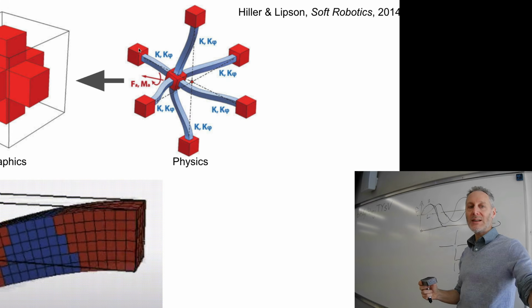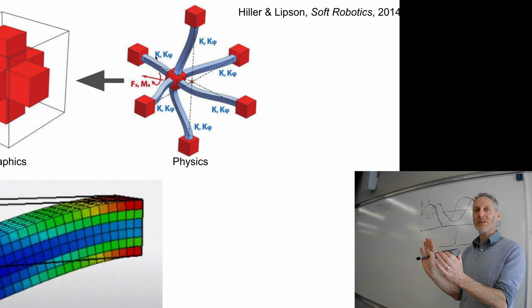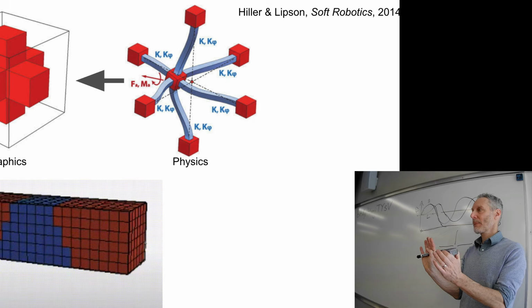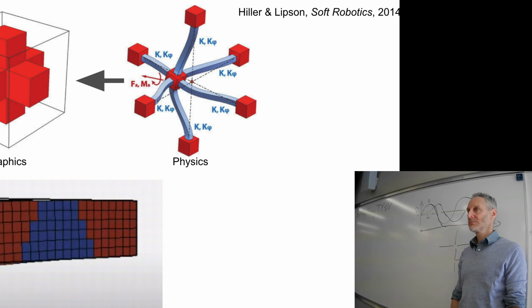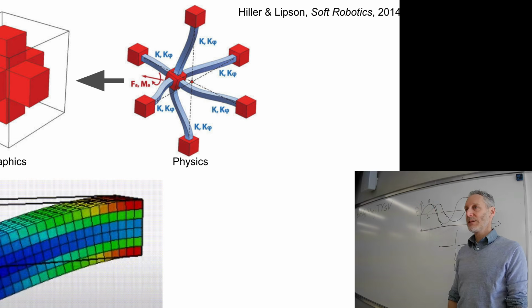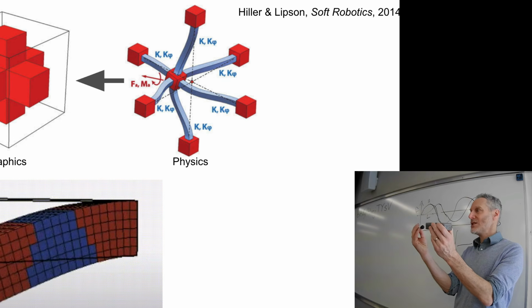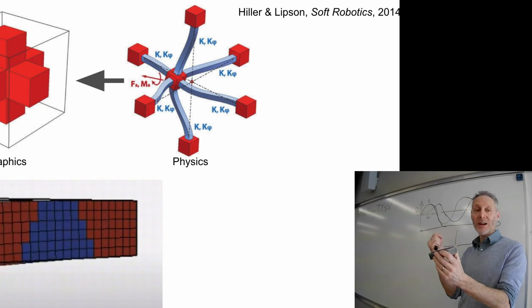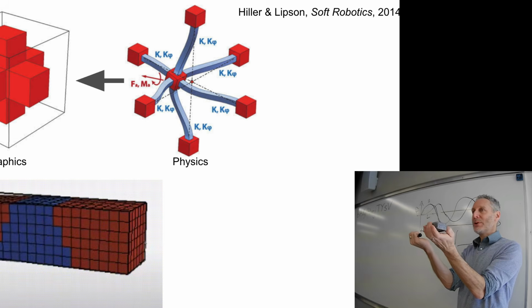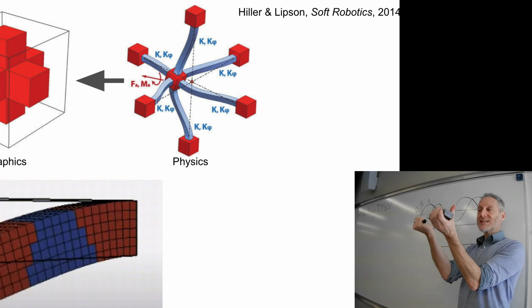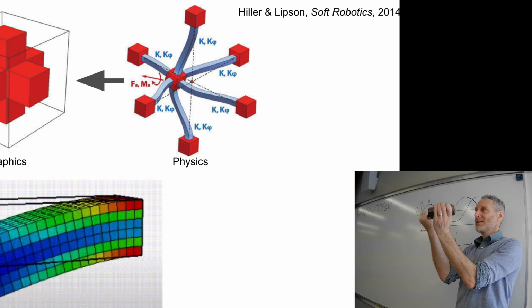Here we're getting fancy, and we can set how much it resists pushing and pulling in different directions. So far, so good? Anybody want to guess about what K sub phi is now? Like torsional stiffness? Torsional meaning related to torque, which is rotational force. How much that beam is going to resist rotational forces, and I never get my yaw, pitch, and roll right, but K sub phi is going to dictate how much that beam resists this.